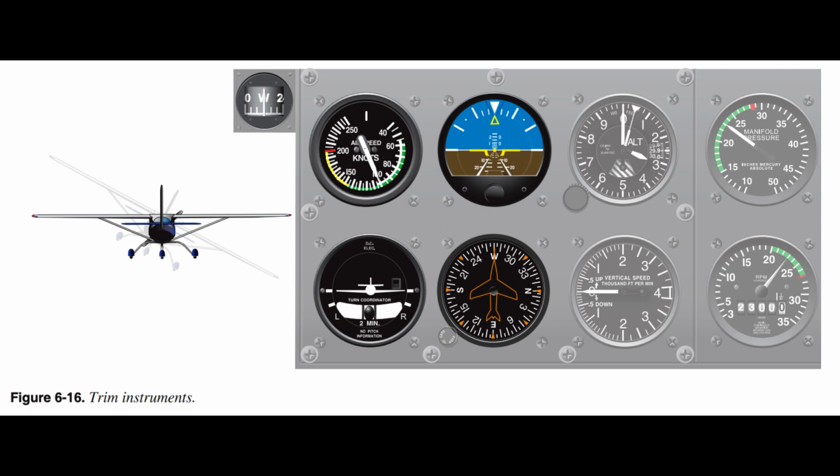Pedal trim is required during all power changes and is used to relieve all control pressures held after a desired attitude has been attained. An improperly trimmed helicopter requires constant control pressures, produces tension, distracts attention from cross-checking, and contributes to abrupt and erratic attitude control. The pressures felt on the controls should be only those applied while controlling the helicopter.